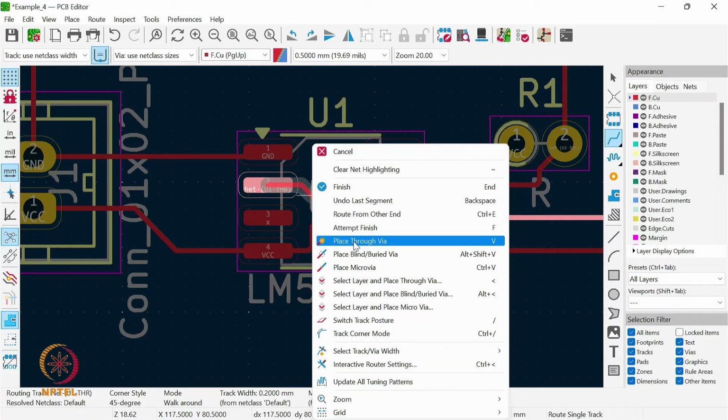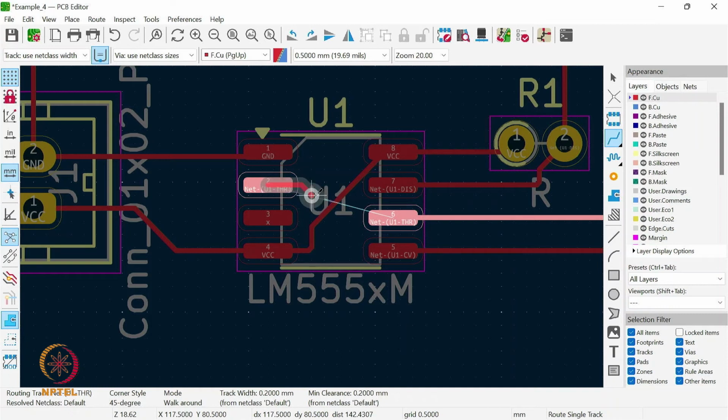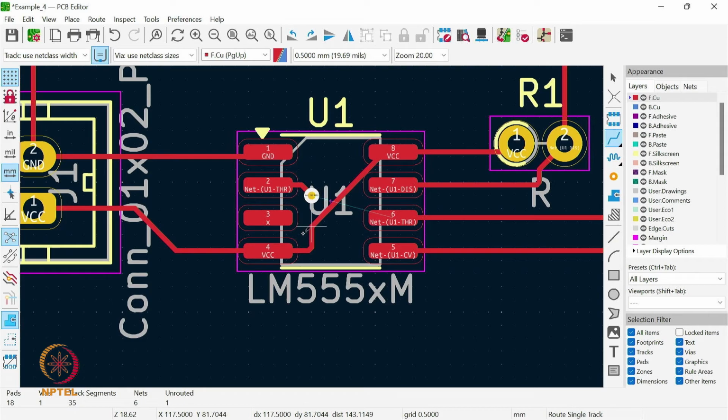We will route our signal through the back layer and will again come back into the front layer after passing this space. So we put the via here. You see, when we have placed this via here, this via appears here.